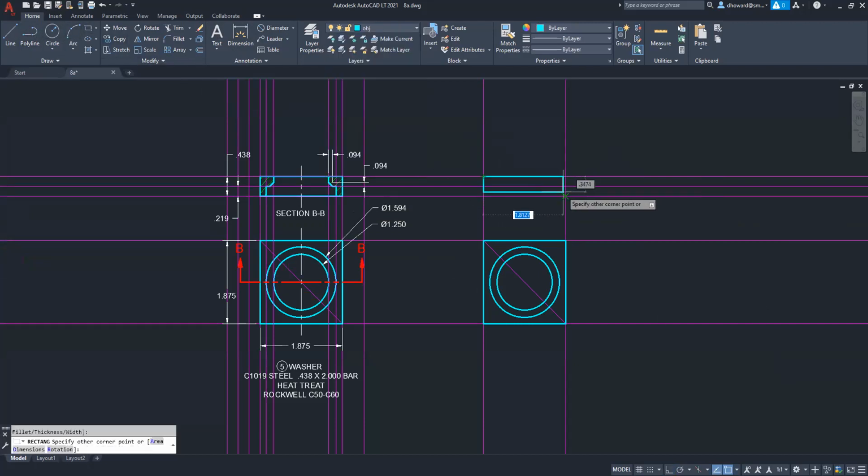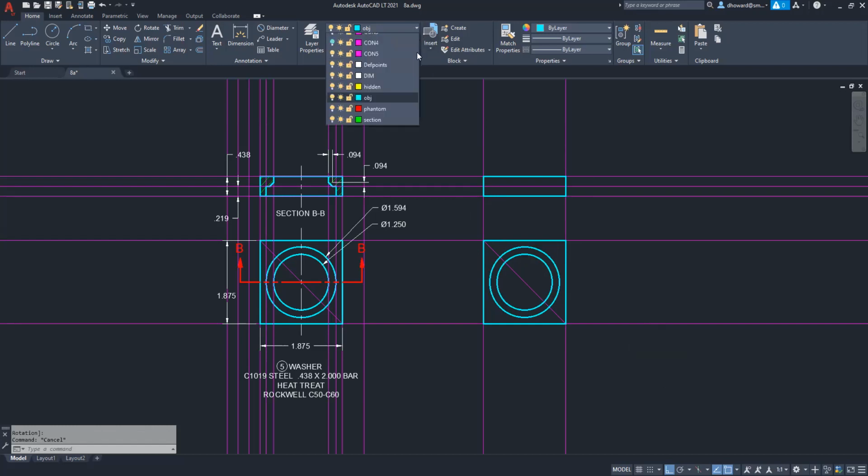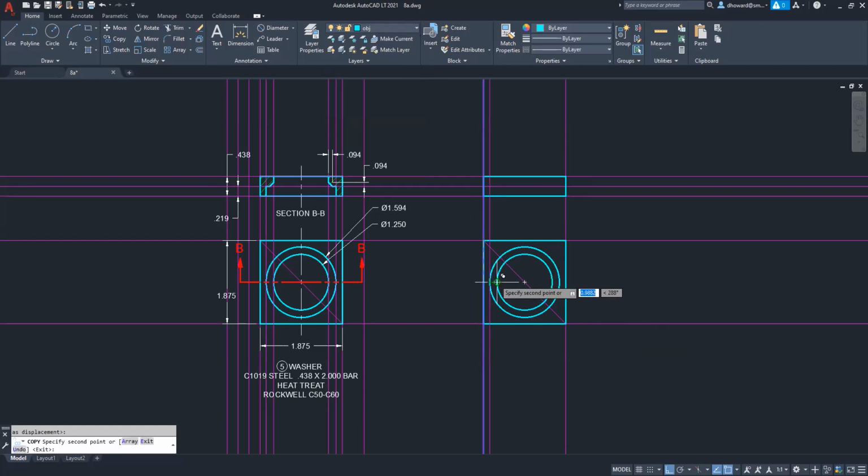And there is this square washer in its side view. And the reason I did the view in section is so that we could dimension it. So we need to bring up these lines from this guy. Just click on the corners here, or the quadrants. There you go.